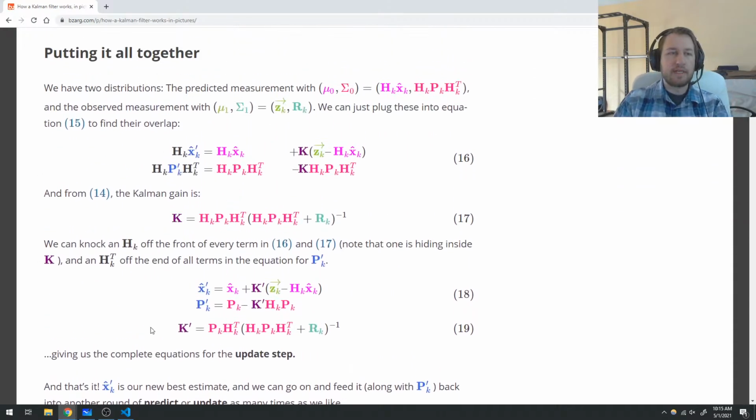What we need to do is say, we have this measurement, but based on this measurement, what is the position, velocity, acceleration? How does that influence it? How sure are we, and how do we choose this happy medium between the prediction and the update step? And the K matrix, which is the Kalman gain matrix, is the thing that tells us how much you trust the measurement and how much you trust the prediction.